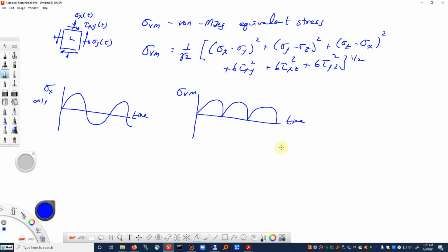And so that's a problem, potentially, when we talk about strain amplitudes, or stress amplitudes, and applying this to, say, an SN curve. Now our stress amplitude is half what we think it ought to be based on the original picture for sigma x. Okay, so this is an issue. Some people have overcome this issue, or they like to think they have, by using something called a signed von Mises stress.